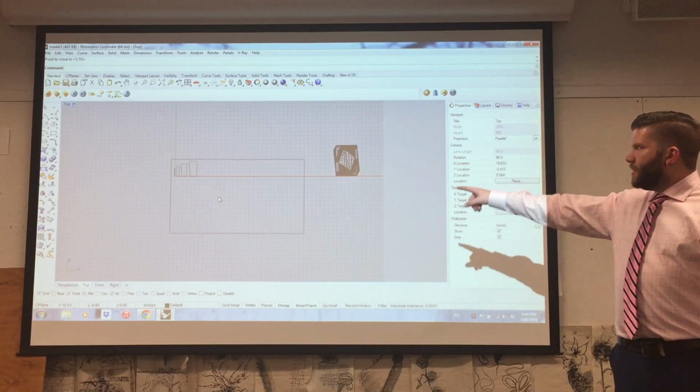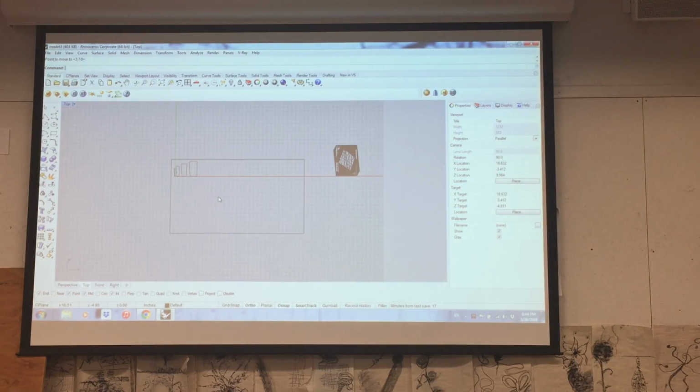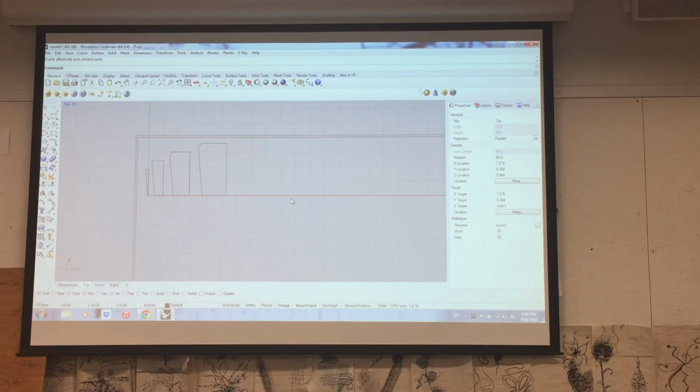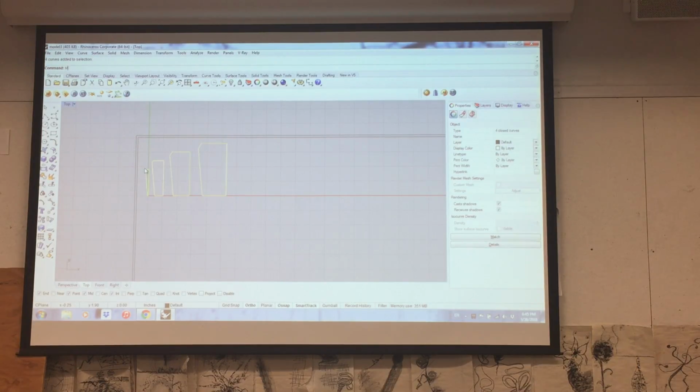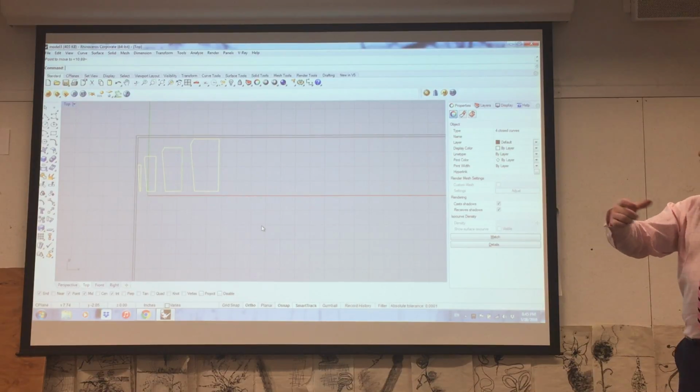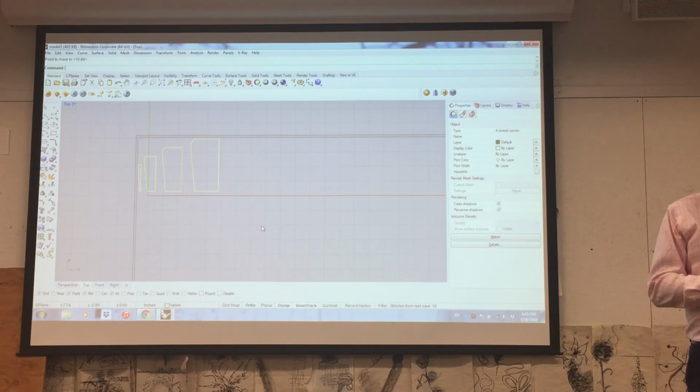And you keep all of your section cuts about 1/8 of an inch away from the outside. That's kind of just the margin of the laser cutter. It won't go all the way to the edge, but if you give yourself like 1/8 of an inch, that's pretty safe. So that means I could move these sections over here, right? And it would still be safe, and it would give me a tiny bit more room. And the closer you get them together, the more you can fit on one sheet. I would not have them touching because the laser itself has a kerf as well. I know you know what a kerf is. It's very small, but it's measurable.